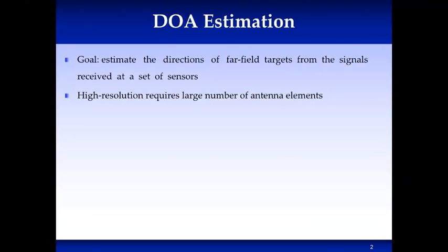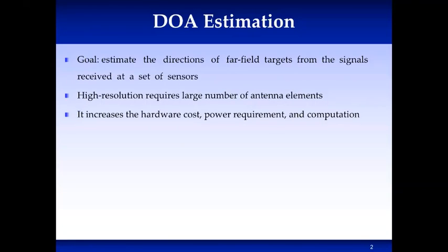DOA estimation is an important problem in many engineering applications. Here the goal is to estimate the direction of far-field targets from signals received at a set of sensors. In these applications, high-resolution direction of arrival requires a large number of antenna elements. However, this increases the cost and power requirements as well as the computations, since high volumes of data are generated.